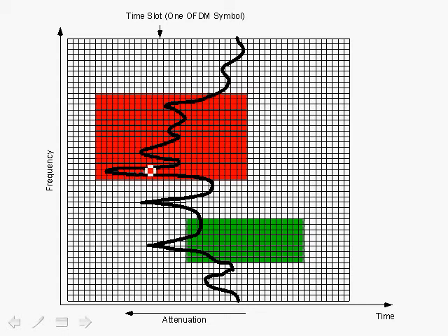In fact, it would be better if the carriers within a data region were actually selected from a group of carriers across all carriers such that they are not adjacent to each other, and that is, we perform a permutation of the carriers so that within a data region the carriers are not actually adjacent but have gone through a permutation.